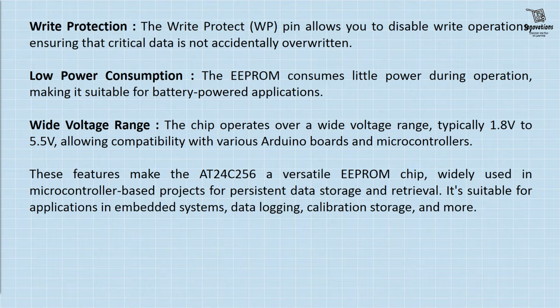Now, write protection. The write protect pin allows you to disable write operations, ensuring that the critical data is not accidentally overwritten. Low power consumption. The EEPROM consumes little power during operation, making it suitable for battery-powered applications. Wide voltage range.